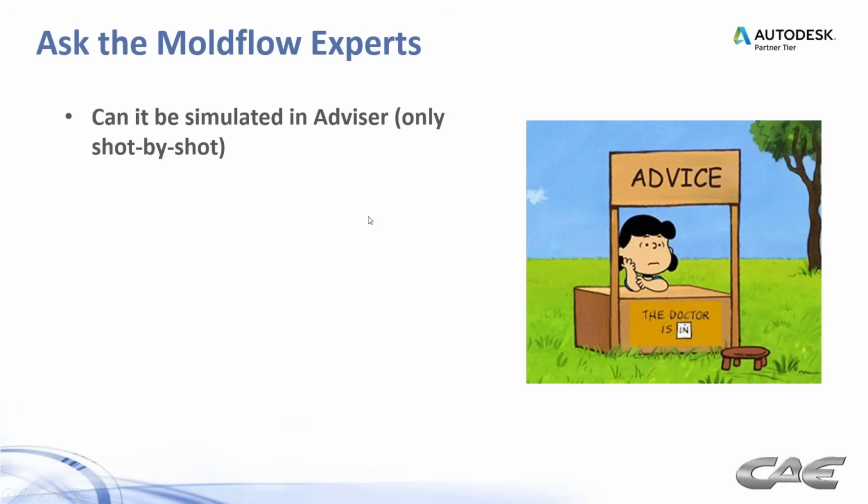For those of you who don't know, there are two Moldflow programs. One's called Insight, which is the more in-depth, fully capable manufacturing solution of Moldflow. Advisor is more what the name implies. It's an advisor analysis. I don't like to call it a stripped down version of Moldflow, but we'll go with that for now. But can overmolding be simulated in Advisor? The answer is no, not explicitly, but we can do the same things in Advisor that I mentioned before when we separate the shots. We just can't see how the two shots interact with each other.